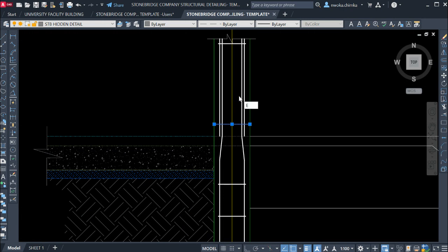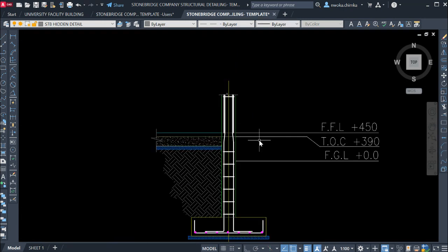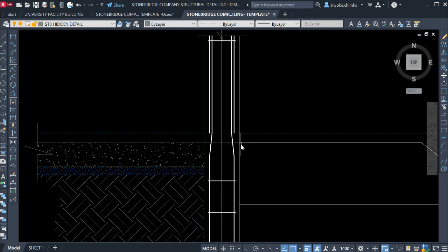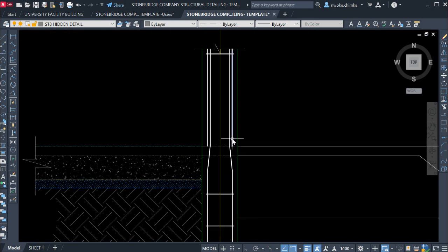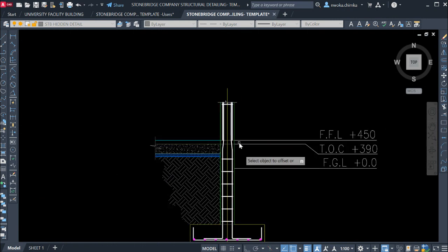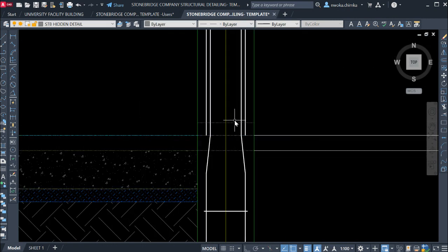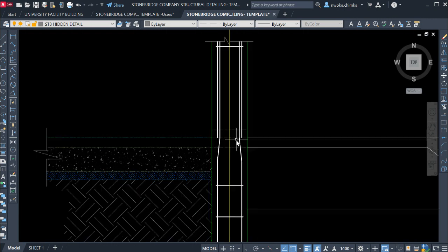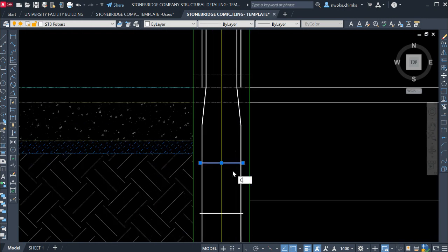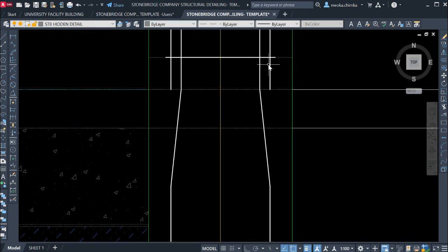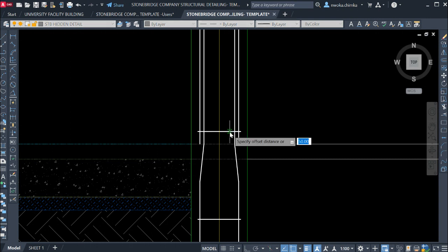So I'll first of all take this off, and then we can go to offset again our first link, which is 50, as we just did on this other first one here. So offset this again, 50 again, then match properties, or just copy. Let me just copy a link, because I don't want to waste much time on this video. Copy and paste it here, and then remove this reference line. So now I can go and finish up the spacing of 200.